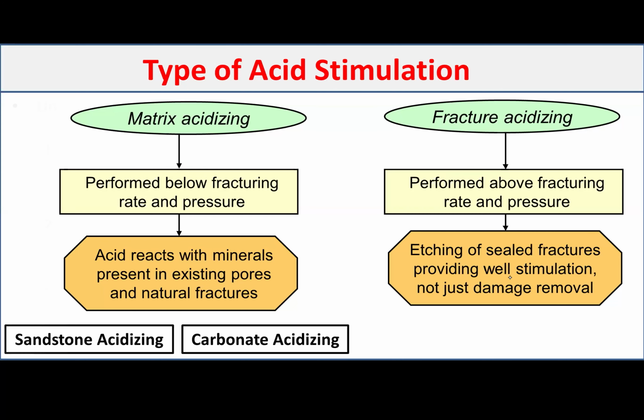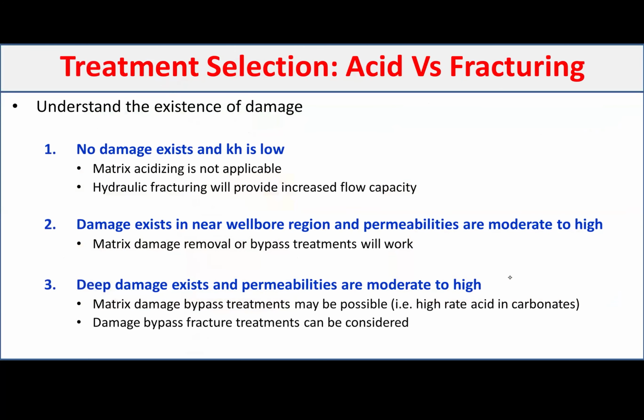So maybe that's one more thing: how do you select between acid versus fracture treatment? That's a main key point that as a petroleum engineer or completion engineer, you like to distinguish. So when you are using acid fracture, or acid, or matrix acidizing, that will depend on the type of the formation that we are dealing with.